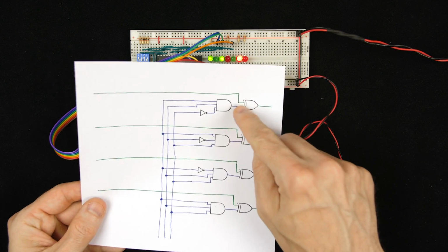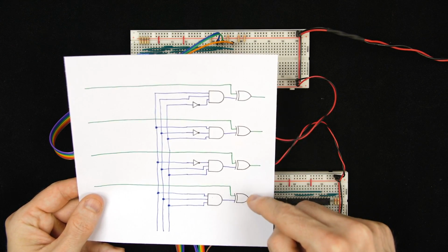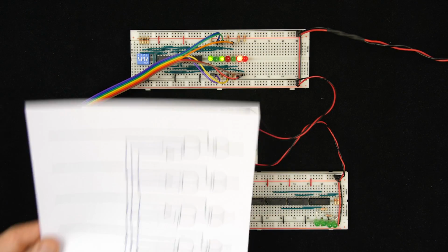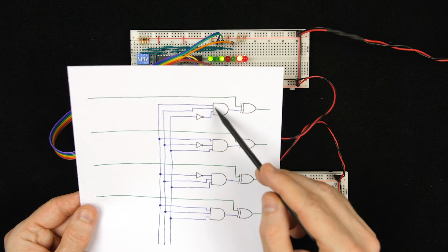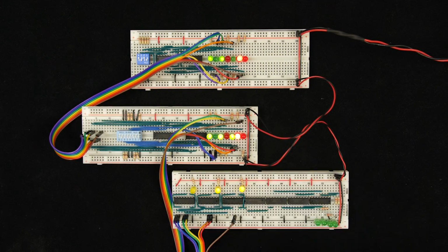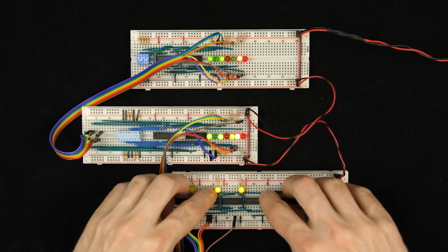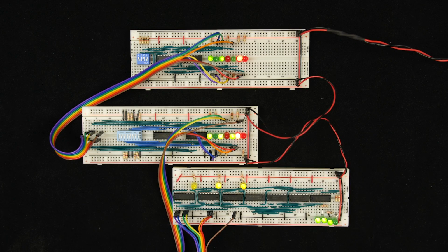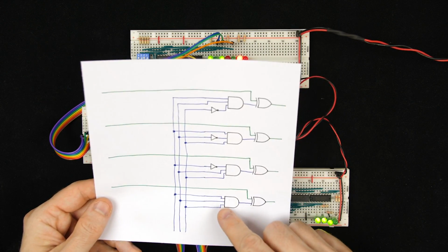So there we go. We've got the 4 outputs of the AND gates hooked to 4 of the inputs of the 4 XOR gates. Then I've got a bunch of these connections here on the inputs of the AND gates to hook up. A lot of them are hooked to each other, 2 inputs connected to each other, so I'm going to try to hook these up as efficiently as I can. Okay, so that's all of these connections, I think.